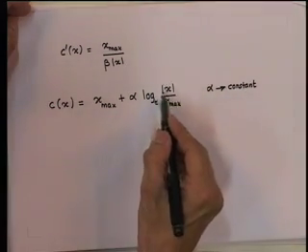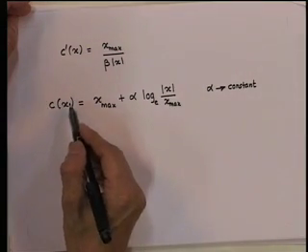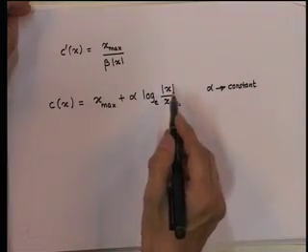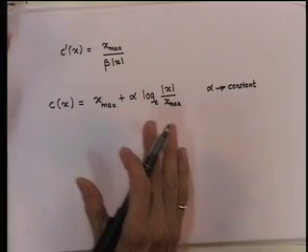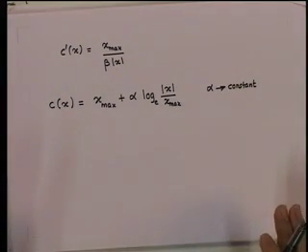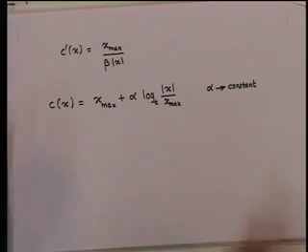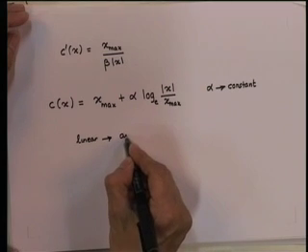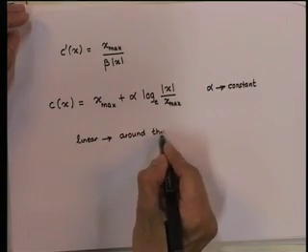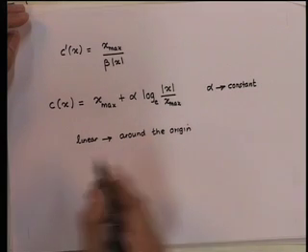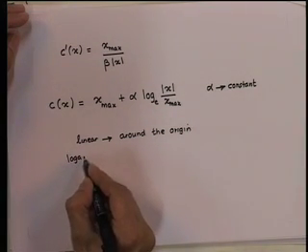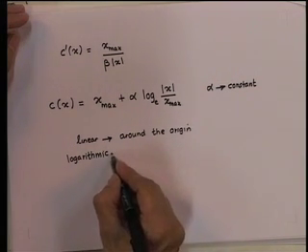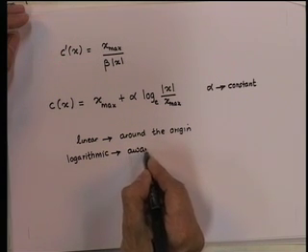Now, for small x, C x assumes very large value. Therefore, in a practical situation, to avoid this technical difficulty, the compressor characteristic is approximated with a function which is linear around the origin and it is logarithmic away from the origin.